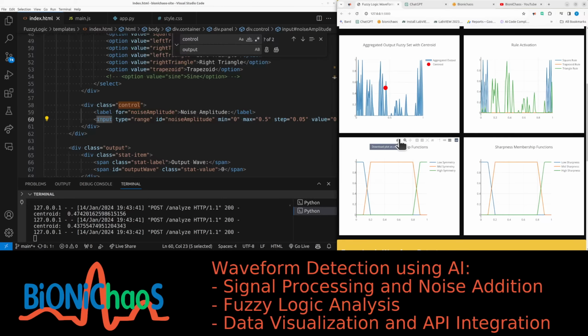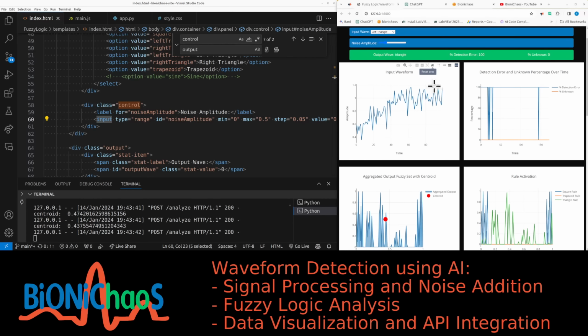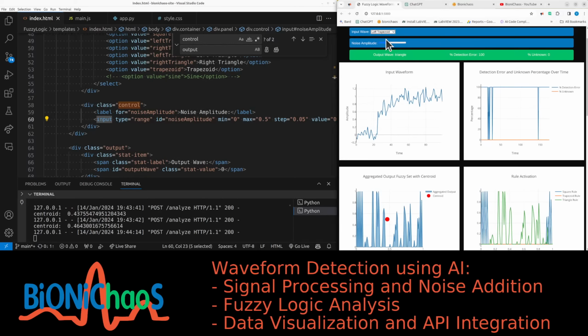Visualize membership functions: plot these membership functions to visually confirm that they cover the entire range of values. This will help you see if there are any gaps or overly narrow coverage in certain areas. Validation: test the membership functions with input values spanning the entire range. Ensure that for every input value, the fuzzy logic system produces a meaningful output. This means that each input value should activate at least one membership function to some degree.